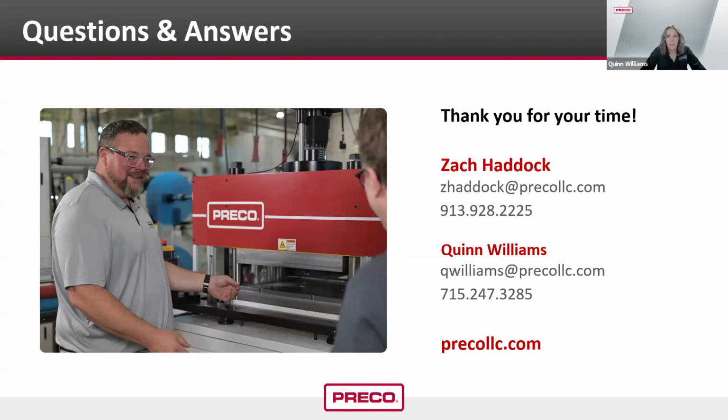All right, one more. Can I just run full tonnage all the time? Absolutely. And there's nothing wrong with it. I feel like I have a pretty strong argument that if you're doing a lot of job changeovers during the day, say 4 or more job changeovers throughout the course of a day, it's not worth going through the exercise of changing the tonnage.